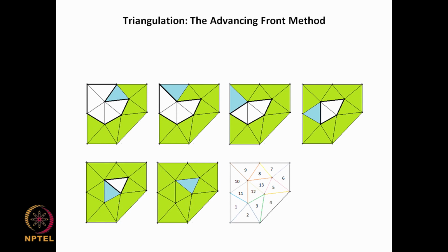Any correction of the triangulation is to be done after you have triangulated. So, after you have triangulated, you can look at each triangle and see what is the aspect ratio, and take adjacent triangles and see if there is a better way of doing this triangulation by doing this circumcircle option and see whether some correction can be made after triangulation.